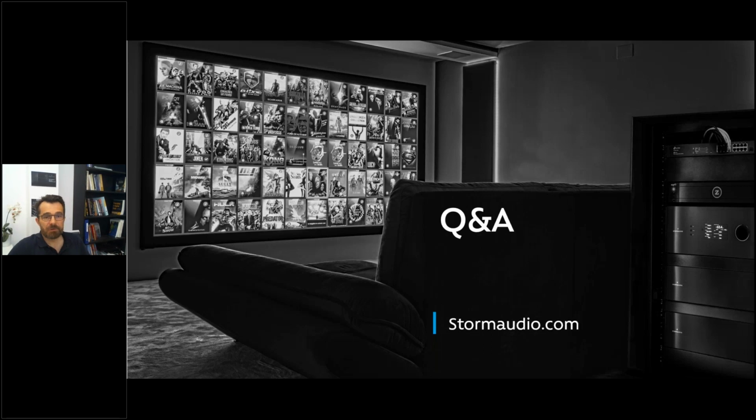And then the last question is about, do we have to invert the subwoofer in the back? No, as I mentioned, you're not doing physically a dual bass array, but the way the system works as a support, it compensates for the reflection. So if you have subwoofers in the back wall and subwoofers in the front wall, in a way, Dirac ART will work on the phase so that it removes the reflection. So do nothing on the phase, let the system do it.